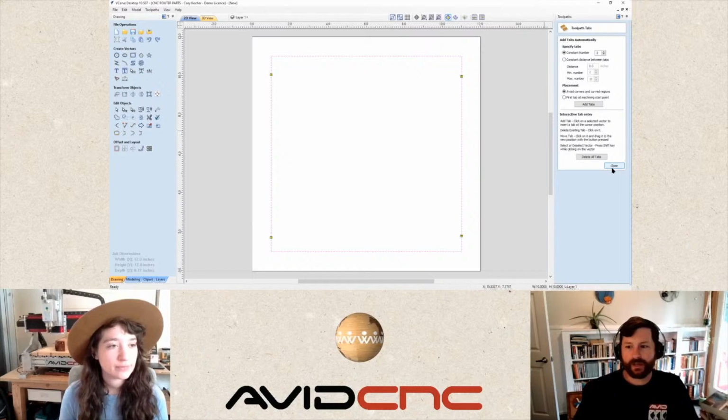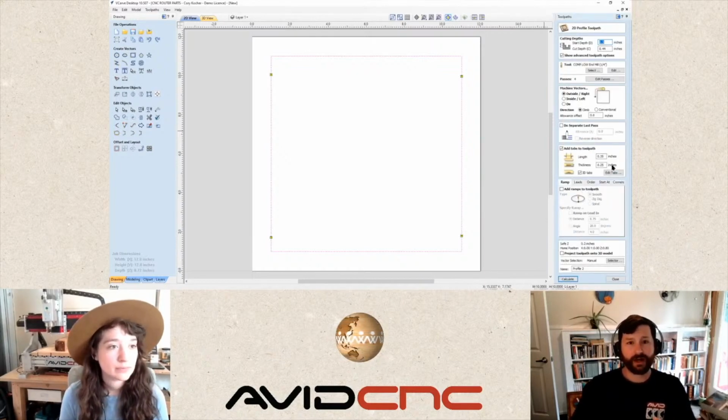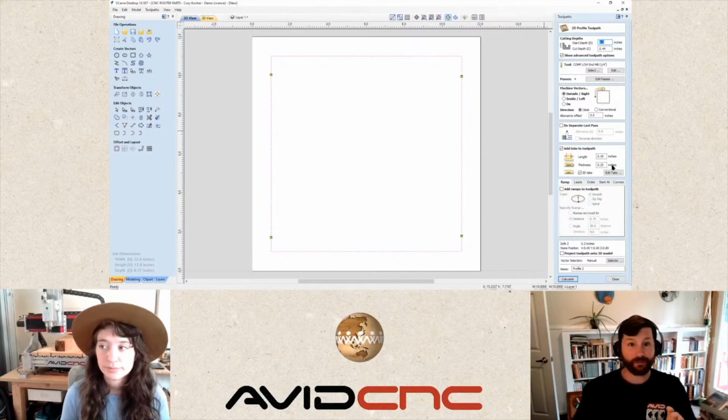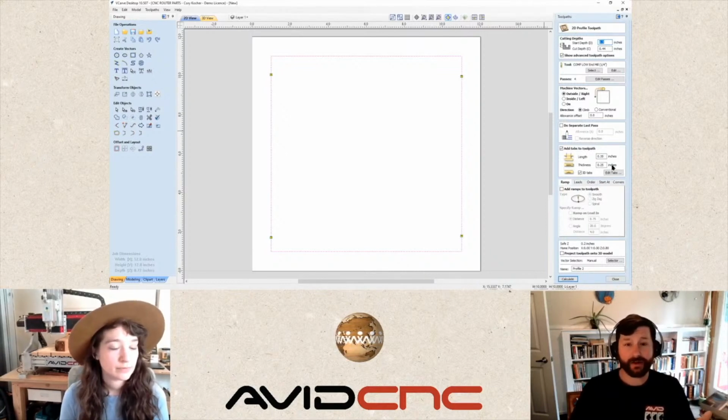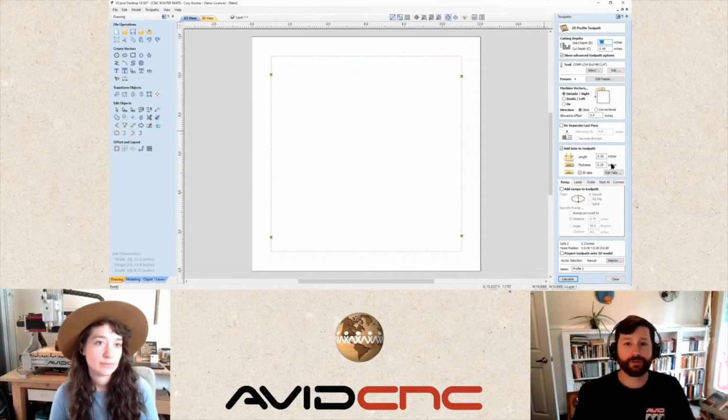Yeah. And if you have a lower quality plywood, or you know your plywood has more voids, the solution might not be just to make really big tabs, but just increase the amount of tabs that you use. And so where you normally might use 2, maybe use 5, because essentially you're setting 1 or 2 of those up to fail because of voids, and you're still going to have more than 2 points of contact when you get all the way around.